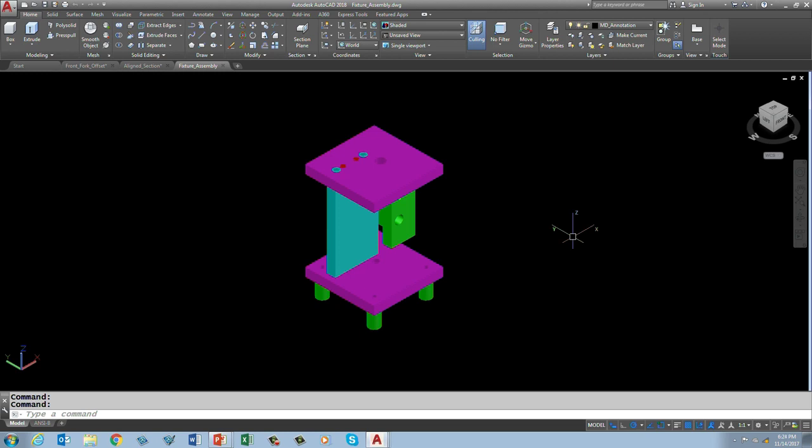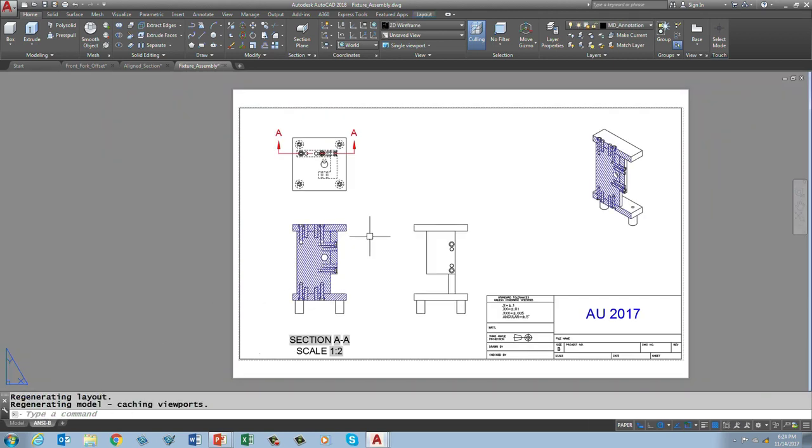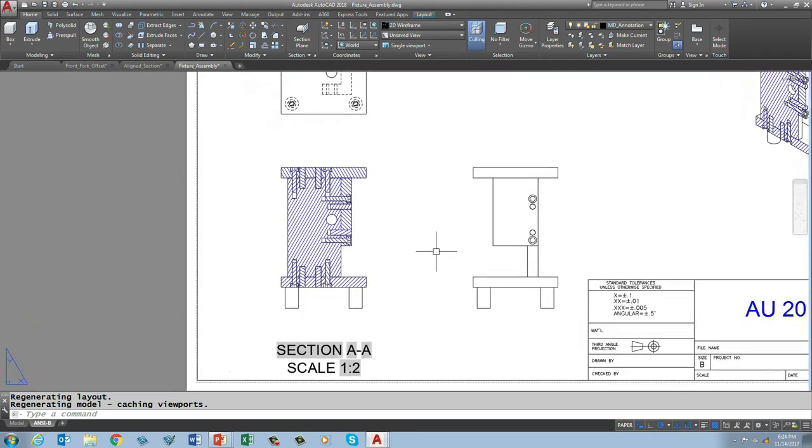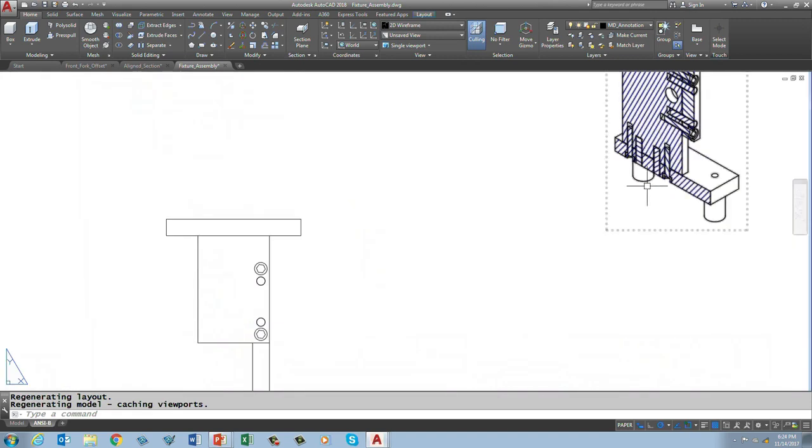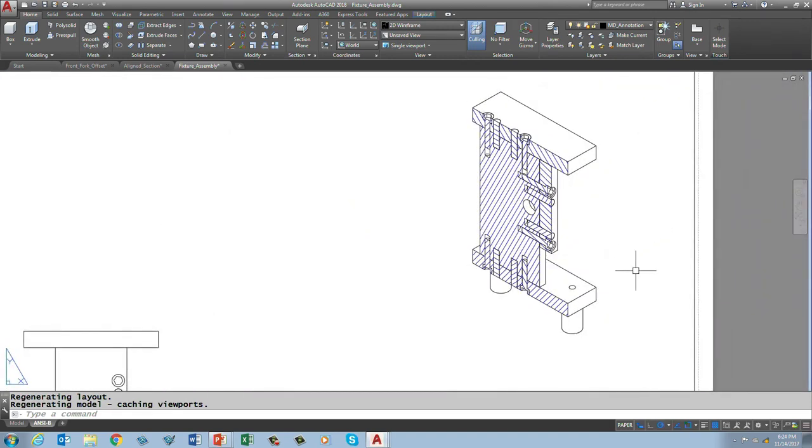Now, it's already done for you. How nice. All right, well, not quite. This is technically totally wrong. It's bad. This is like bad CAD, right? Because we would never section a full section through that part to get what we want. Now, some people may say this is okay, the ISO view, and that's okay if that's what you like.